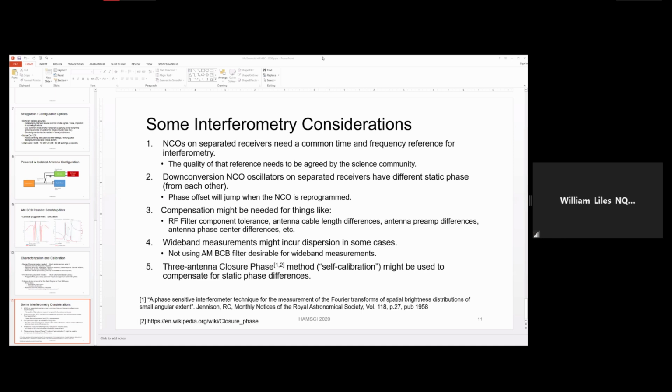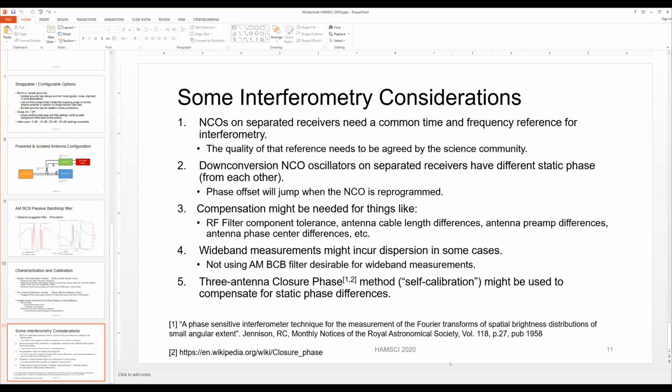But one of the questions is, how good is the reliability of the relay switches, particularly over temperature range? Like if we use this very high up north, below zero temperatures. Yes, we have not looked at the temperature reliability of the relays. The relays are specified as 1 million cycles, and so they should have a fairly long reliability. I'm not aware too much of the temperature limitations.